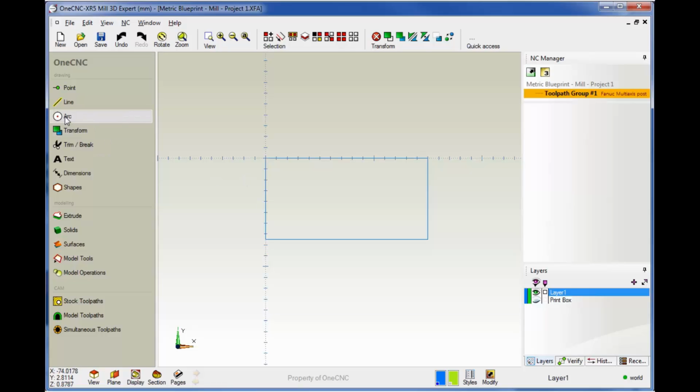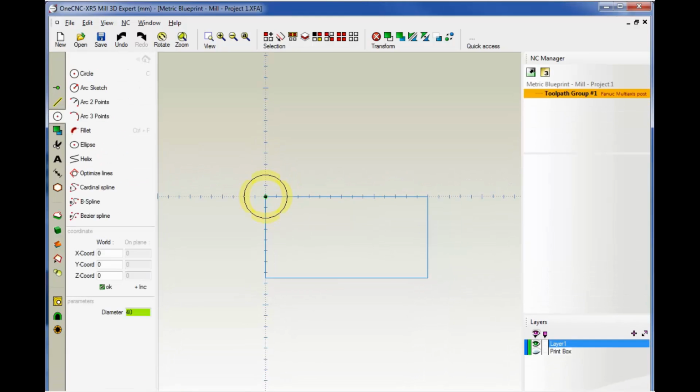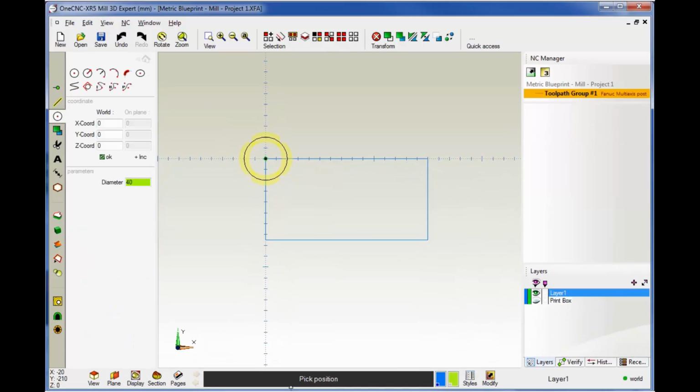We'll come back over here to arc. All right, now here's our fillet command. Because I have limited screen capture area, you're just seeing icons for the arc options, but if I expand this a little bit, your system's going to look like this, where you get the icon and a brief description over here. The main point now is we want to select the fillet command, which is right here, and down here where it says fillet radius, I'm going to type in 25.